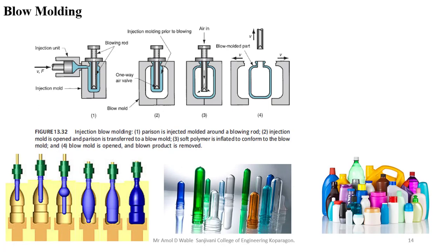from thermoplastic polymers. So blow molding is done in two steps. First, fabrication of the parison, and later this parison will be blown into the cavity, and after blowing into the cavity you will get the final shape of your component. So here you can see the different stages. Initially this blue part will be called a parison. So blow molding consists of an extrusion of a heated tubular plastic piece, which is called a parison.